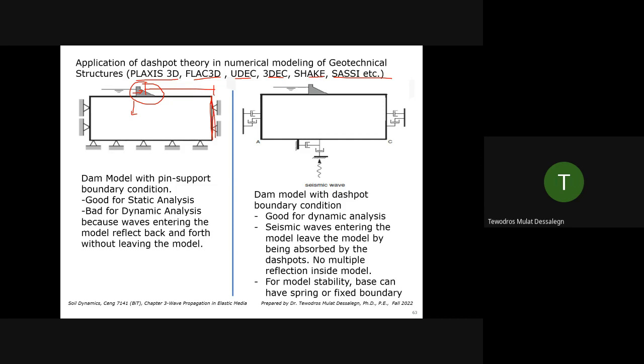You can determine the boundary size, the length of your model, by doing some sensitivity, by checking stresses and displacements around the boundary. When they get almost negligible, that's your boundary. Now, dam model with pin support boundary condition. This is good for static analysis. It's perfect. That's okay.